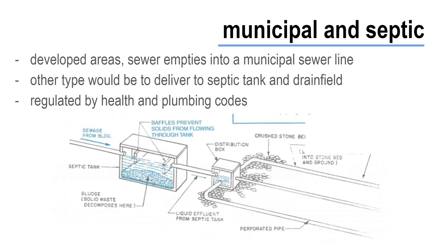So the septic tank holds the solid waste while it is decomposed by bacterial action. Then the liquid passes through the baffles and flows out of the tank into a distribution box. And then the distribution box diverts the liquid into leach lines.